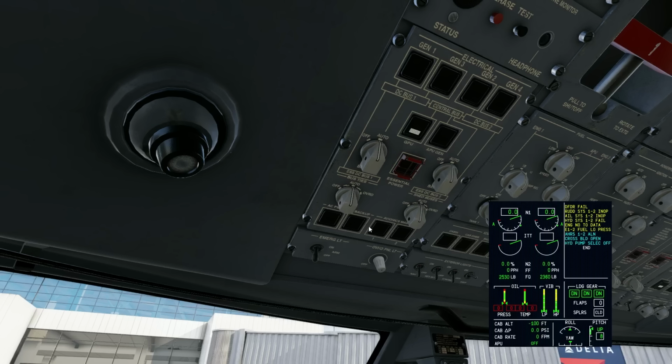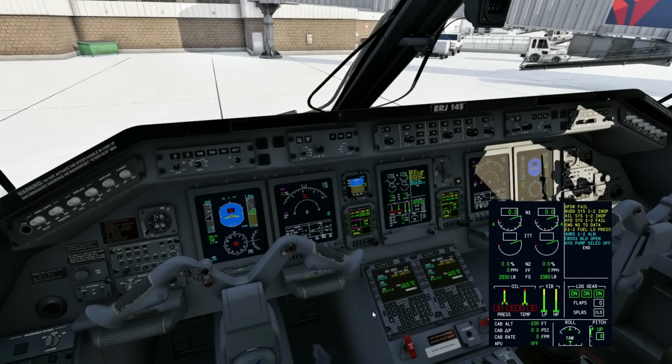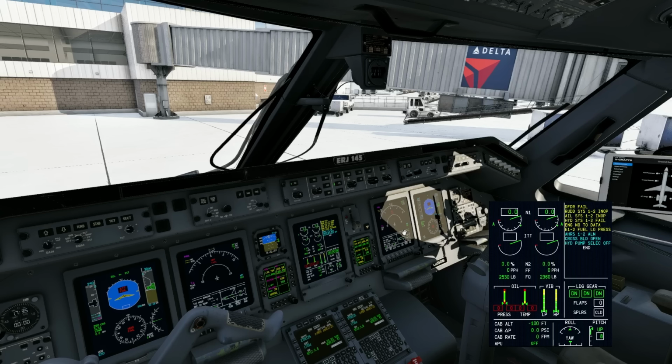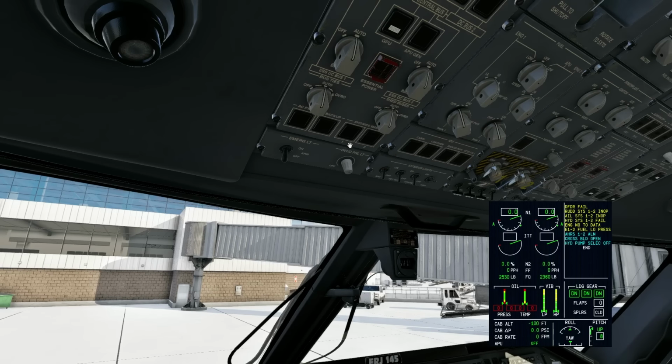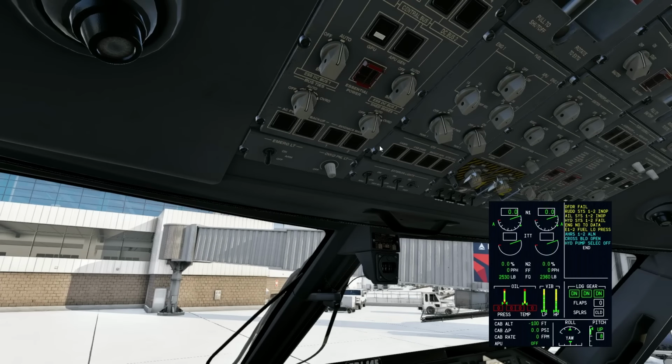We have a backup battery. What the backup battery does is it is actually the battery that powers the electrical control logic. So without needing these batteries, these power the airplane. That battery powers the electrical logic in an electrical emergency. We talked about our avionics push button, so remember that avionics 1 controls PFD1, FMS1, and MFD1, and avionics 2 does the opposite.